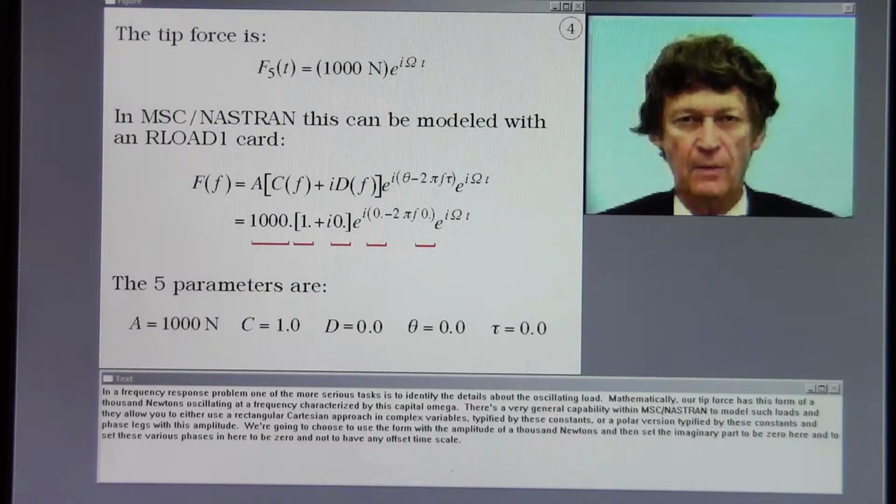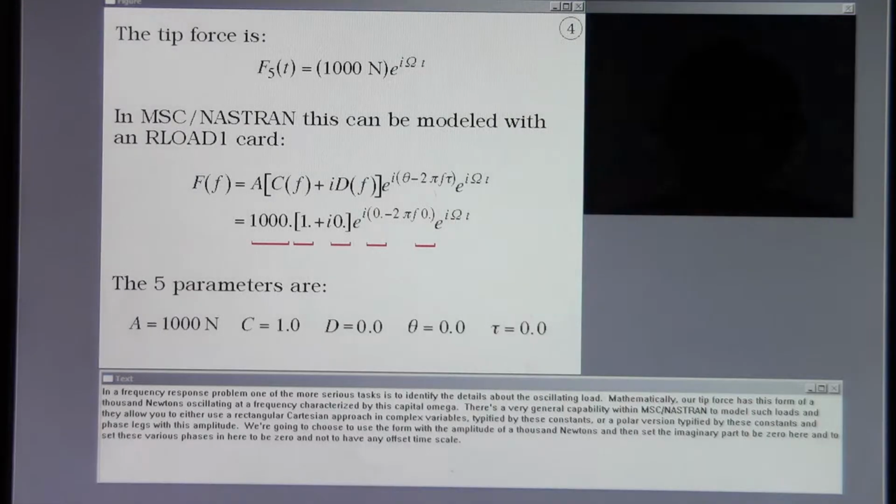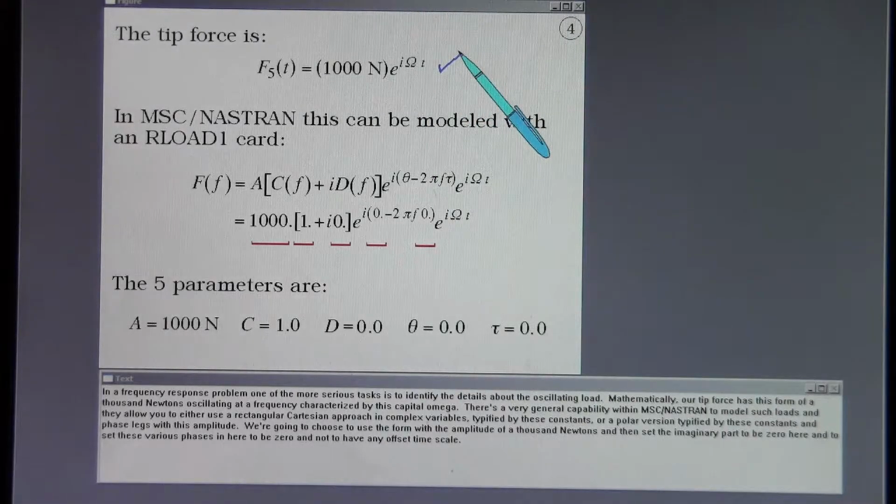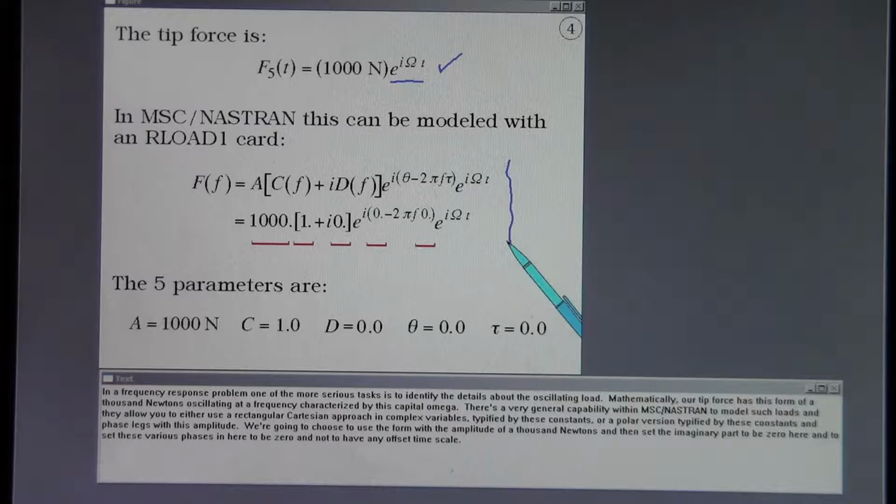In a frequency response problem, one of the more serious tasks is to identify the details about the oscillating load. Mathematically, our tip force has this form of 1,000 newtons oscillating at a frequency characterized by this capital omega. There's a very general capability within MSC Nastran to model such loads, and they allow you to use either a rectangular Cartesian approach in complex variables typified by these constants, or a polar version typified by these constants and phase lags with this amplitude.